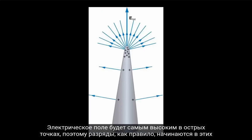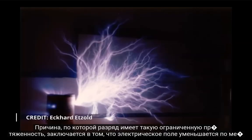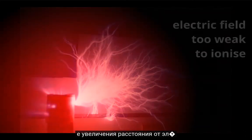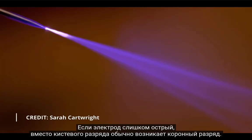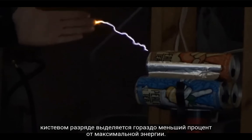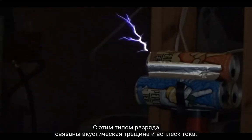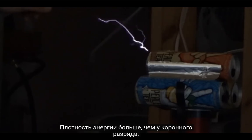The electric field will be highest at sharp points, so discharges tend to start at those points. The reason the discharge has such a limited extent is that the electric field decreases as the distance from the electrode increases. Eventually this will drop below the value needed for ionization. If the electrode is too sharp, a corona discharge will usually occur instead of a brush discharge. Unlike a spark discharge, where a large percentage of the maximum possible stored energy is released per discharge, a much smaller percentage of the maximum energy is released per brush discharge. Associated with this type of discharge are an acoustic cracking and a burst of current. The energy density is larger than a corona discharge.